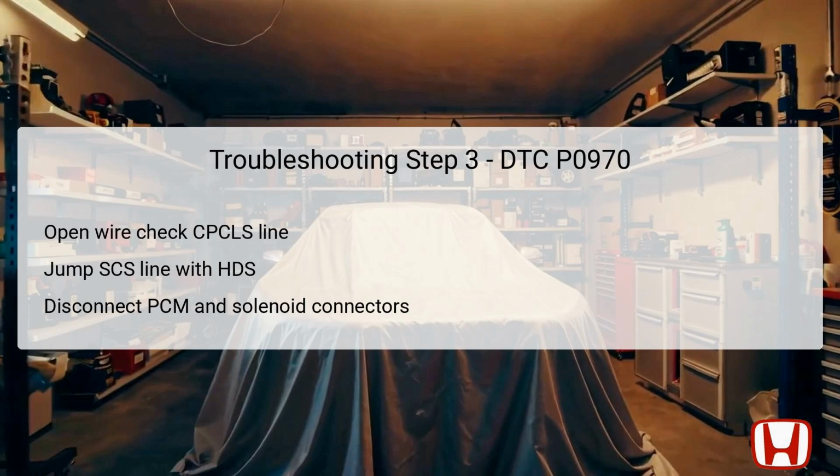Begin by turning the vehicle off and jumping the SCS line using the HDS tool to enable simultaneous checking of electrical paths. Disconnect the PCM connector B and the solenoid wire harness as prescribed. With these connectors removed, continuity must be checked between specific test points: the solenoid wire harness and the PCM. Verify that the solenoid wire harness's connector number 7 matches the PCM's connector number 14.